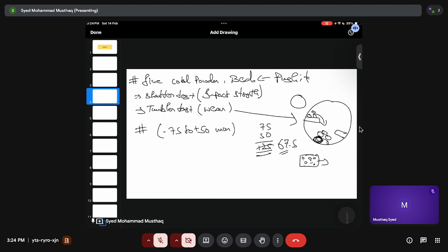In the shatter index, you measure the weight of coke surviving, whatever coke has remained after your 50 mm mesh. So whatever the retained particles above 50 mm, you take, and then you divide it by the total mass, times 100. That will give you that.